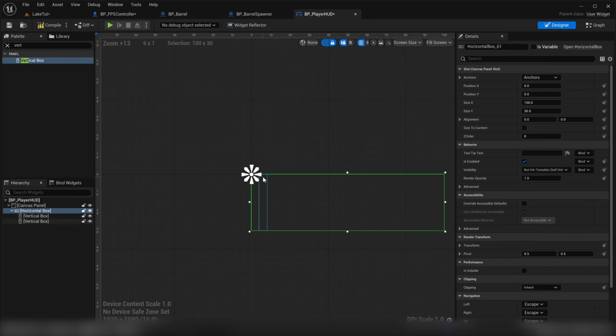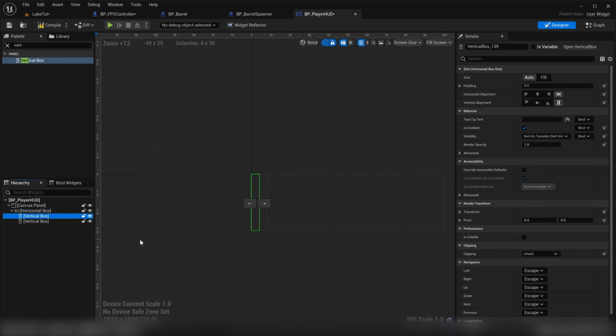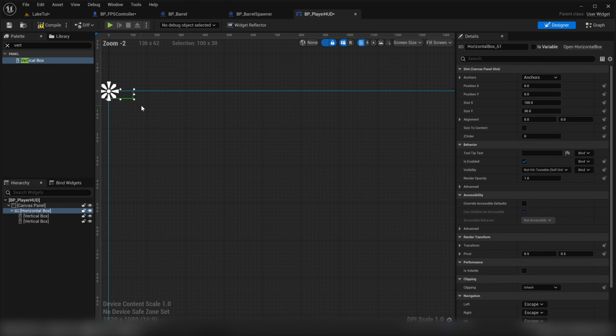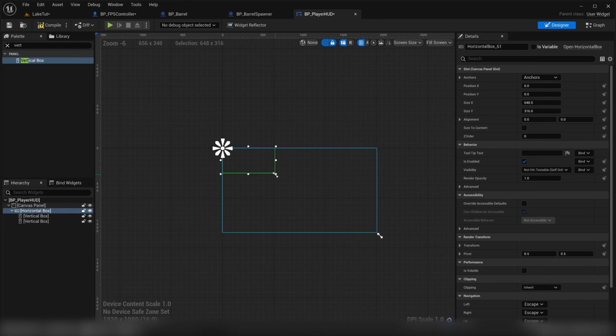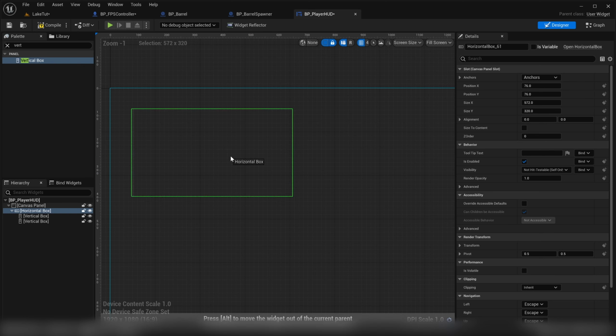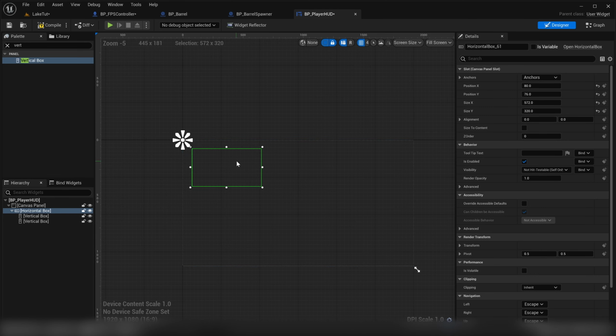And so this flower just basically lets you choose where this is anchored to in screen space. So if we want to anchor this into the top left, we just pick this one here. We'll click that and that'll anchor that canvas panel to the top left. And then if we imagine this is a 16:9 screen, we can pick our horizontal box to be about, might be too big, something like that. And that's just saying that we want all of our content to appear in this area, and we might give a little bit of padding there. So this is the area for UI on the screen.